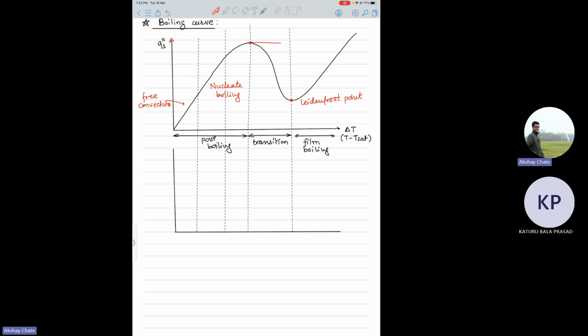They make it a constant flux condition so that you avoid the Leidenfrost point, and without loss of much energy they arrive there. If you don't know this, that is also fine, because that is just a practical trick. But you should know, sometimes they give the boiling curve like this also. But the black line is the main thing.